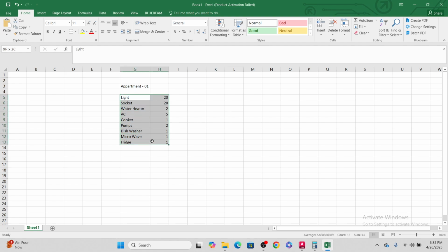When you are making a design drawing, you don't know correctly, because you are designing the electrical. You don't know correctly what kind of light you will use, because the light selection depends on the ID people or the architectural team. So maybe they will use different kinds of lights. Sockets, we know how many we need, but as per the furniture design it can be plus or minus. So as per the design, maybe in some areas you have to use a floor box socket.